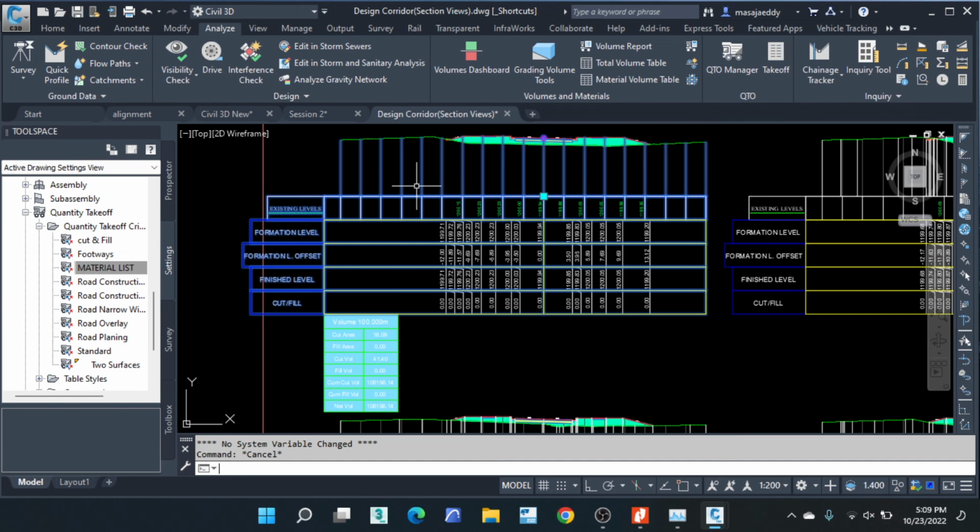Okay, let me also show you how to generate your setting out data. It's data you share with the surveyors when they are setting out the road. So you come to the prospector tool space, you come to the toolbox tab. It's the last one down here. Then you go to, let's use the UK templates. So you shall click on the UK and Ireland reports. Then you go to civil model reports. In the drop down there is an option for alignment.